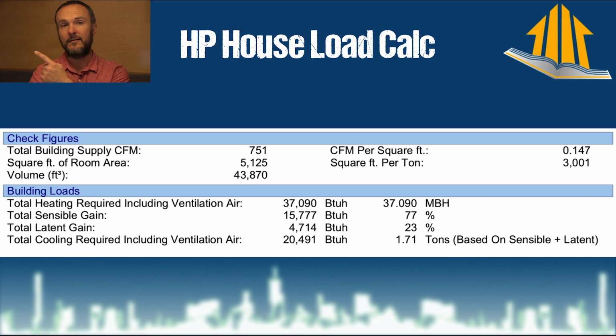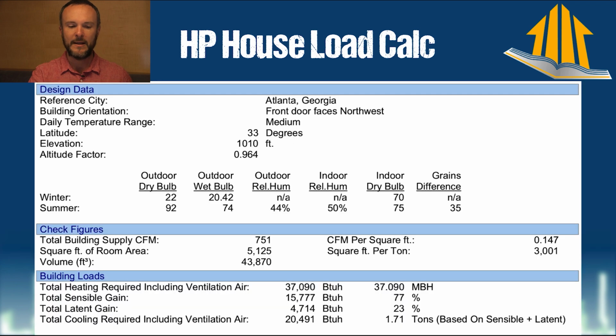I'm going to be using one of these pieces of equipment, the ductless mini split, which is a 95/5 sensible latent split. So that's not going to be good. I definitely need to be planning for, in any high performance home that's going to be reasonably airtight and reasonably well insulated, dedicated dehumidification. Just know that going into it.